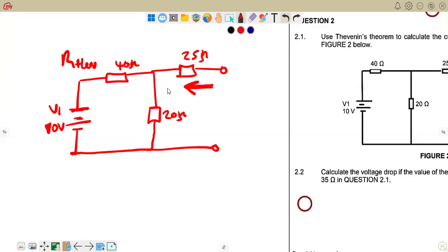From that position, we can see that the 25 ohm resistor, if we are now going in this direction, assuming that the conventional flow is from this direction, means the 25 ohm resistor is actually in series with these two, whereby these two are now in parallel. So, wanting to calculate RTH, this source will not be of much use at that particular time. We are just